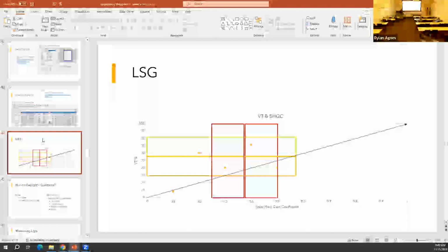And so you design your overhang to account for summer, but allow winter in. In addition, you have to account for landscaping. So you can use natural vegetation to do shading in addition to hardscape. And if you're doing that, you want to make sure that it's going to shed its leaves and allow light in through the winter. That's typically, in my opinion, a better option because it's acting as a natural sunshade. So it's filtering the light and allowing some in and some of it's bouncing out, and it's diffusing it more evenly than if you just had direct solar gain for the winter. But in addition, you're not getting as much solar heat gain from that method.